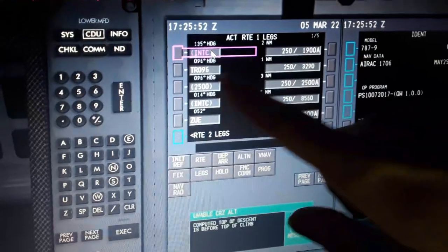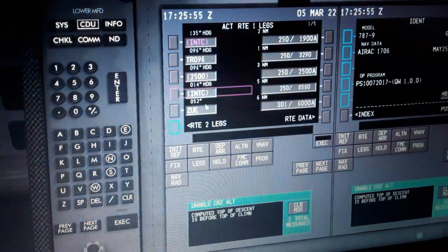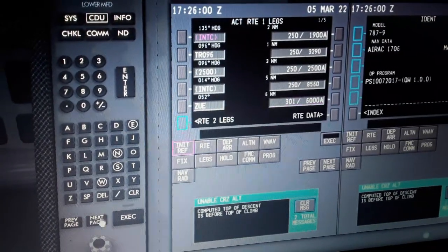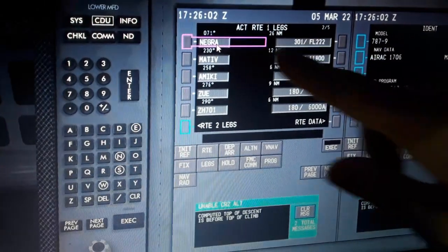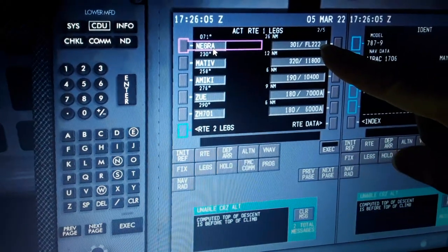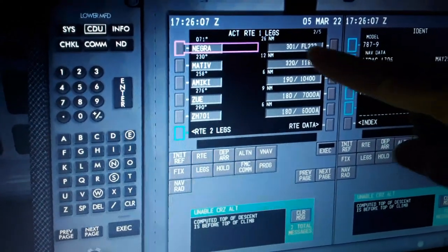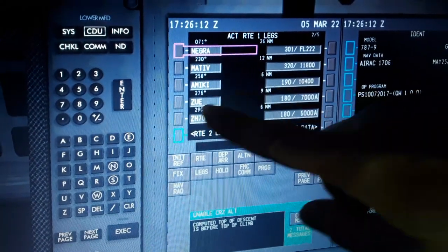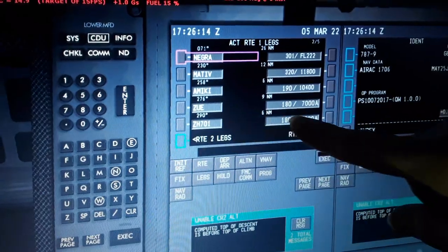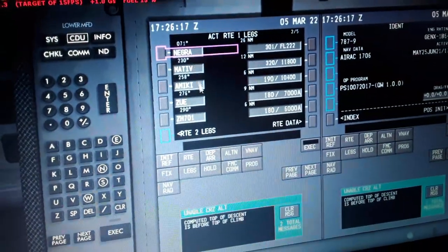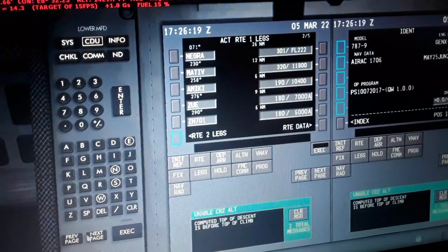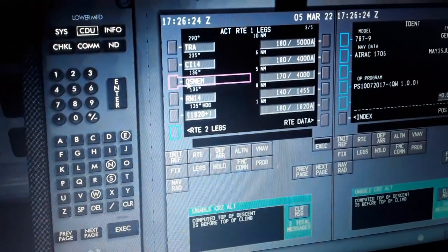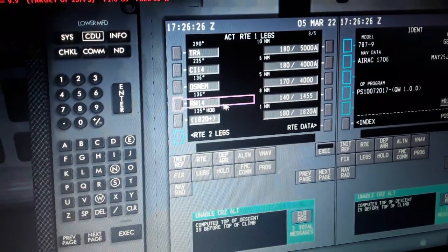So it's displayed with purple over here. It's activated. So you can see first waypoint, ZUE 6 nautical miles, 301 knots, 6000 Alpha, NIGRA 26 nautical miles, 071 heading, 301 knots airspeed, flight level 22,200 feet, MATIV 12 nautical miles from NIGRA, AMIKI 6 nautical miles, ZUE 9 nautical miles, back to the airport, Zurich 701, 6 nautical miles, 108 knots, 6000 Alpha. Then make a left turn here at OSNEM for alignment with the airport runway in the ILS, runway 14,